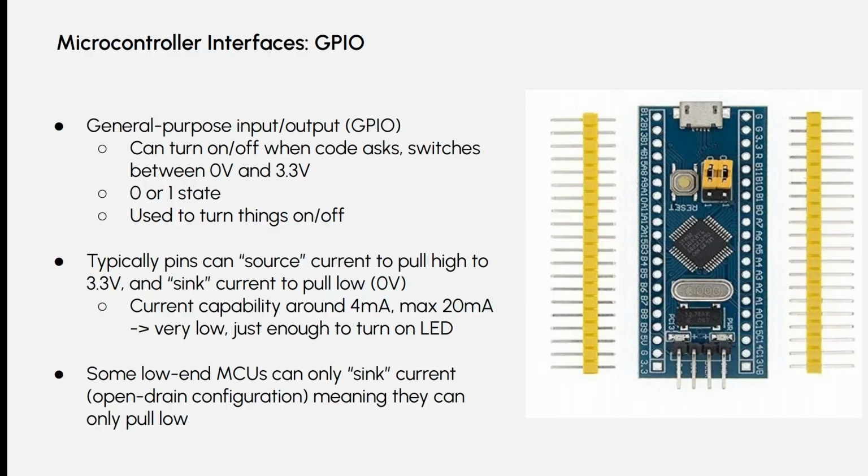This is maybe less common to look at explicitly, but if you ever have something controlling some other device, or any sort of MOSFET switching on a motor or something like that, you're going to need an external controller. You probably will be pulling low sometimes. The current capability is very limited, 4 milliamps, max 20, depending on the microcontroller. This means that if you want to control high-power devices like driving a motor, you are always going to need an external switch of some kind. So that is something to consider. It's about enough to turn on an LED.